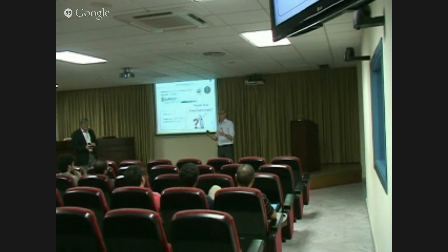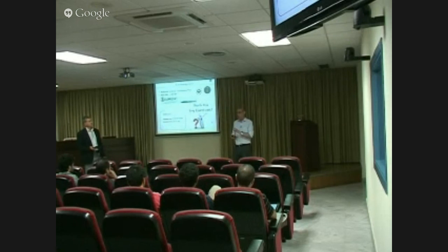So to run that power flow, you need the right external system model, because if you don't have that model, what you get will be the wrong solution. So you need to keep, if not perfect, at least an approximately good external system model to do the contingency analysis.